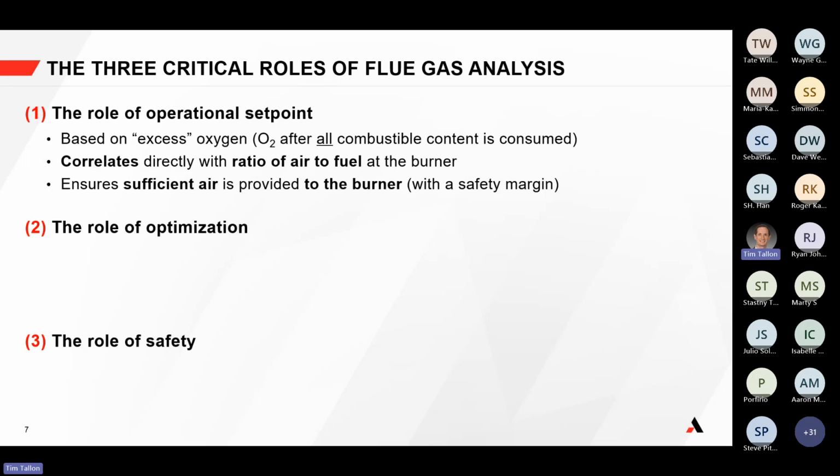So the first reason why an operator would want to measure flue gas analysis in a high particulate application would be to have that set point to make sure that you have sufficient air to fuel at the burner and subsequently adequate product quality, should your process require some type of precise oxygen measurement or precise combustion control for the product quality.